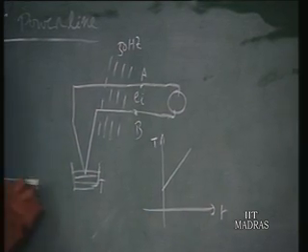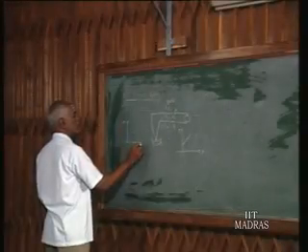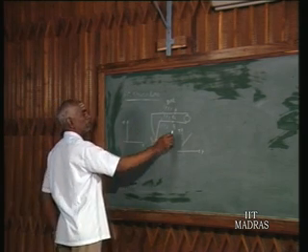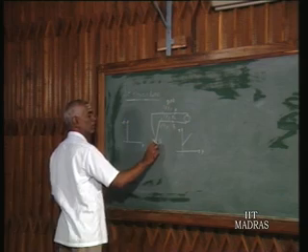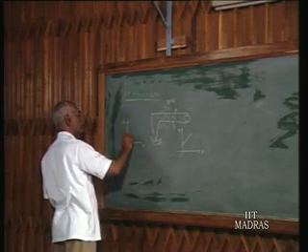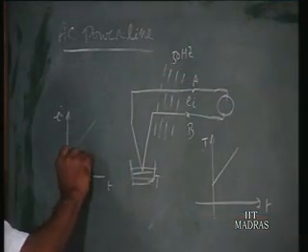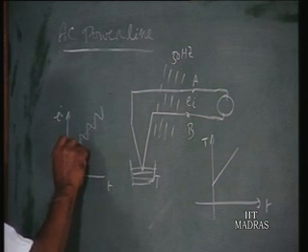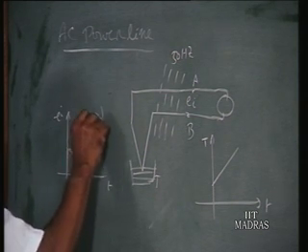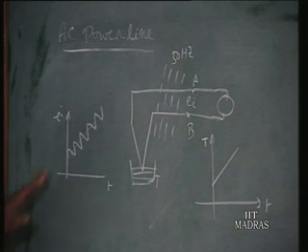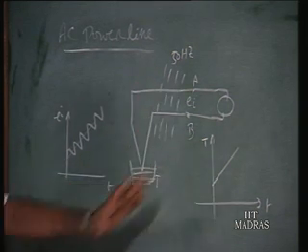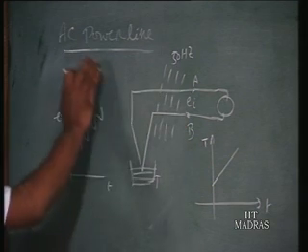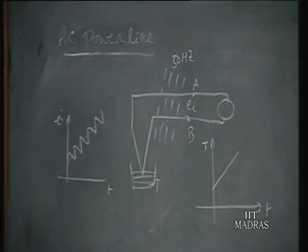We are supposed to have EI proportional to the temperature T, but because of superimposition you will find these variations. This is because the 50 hertz is superimposed. This is due to the nearby AC power line.